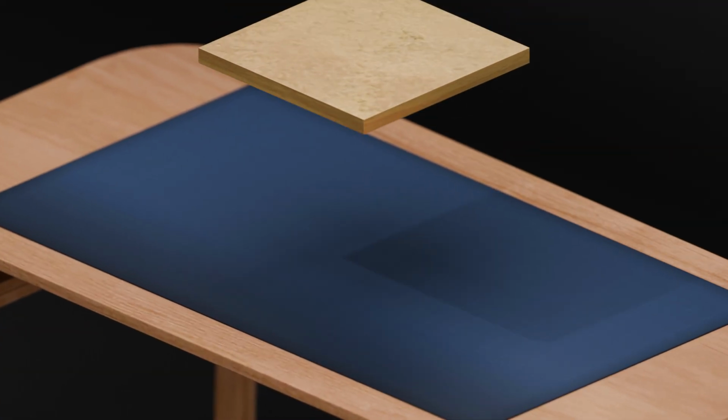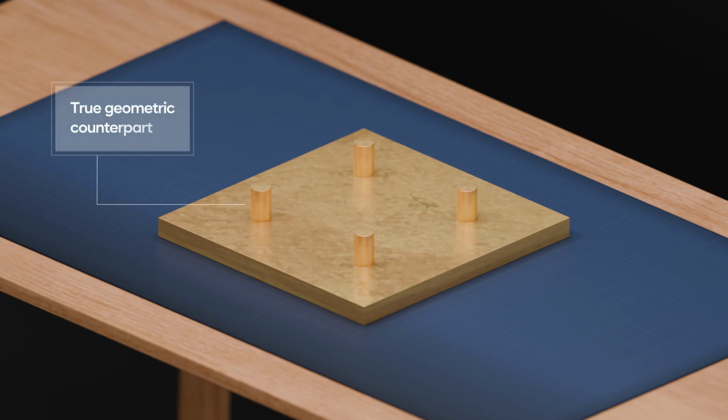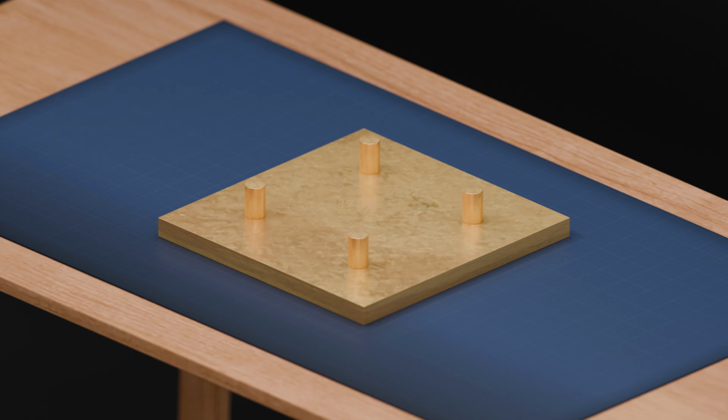What it really does is tell us that the basic location of a datum true geometric counterpart is not locked in place. In other words, instead of being completely fixed, the datum simulator, that's the surface or pin we use to represent the datum during inspection, is allowed to move or slide slightly within the specified tolerance zone. We call that movement translation.